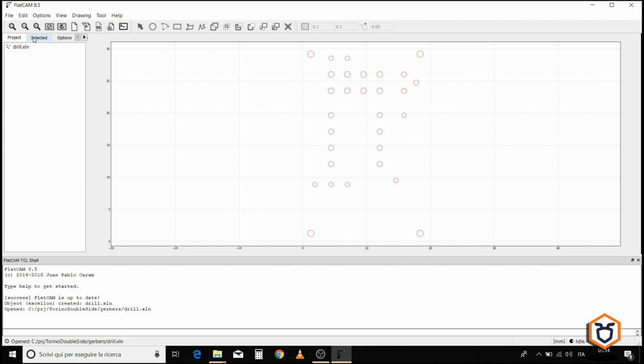Sometimes there is the problem that these holes do not exist, or the number of vias is very low or so next to each other that it's difficult to get a set of holes that can be used for the alignment. As a consequence, during the design of the board, it is recommendable to include some alignment holes, also in the external part of the board. That is not an issue. The important thing is to have at least 4 of them, and they should be easy to locate. They should not really be next to each other, should be distributed on the working area surface as equally distanced as possible.